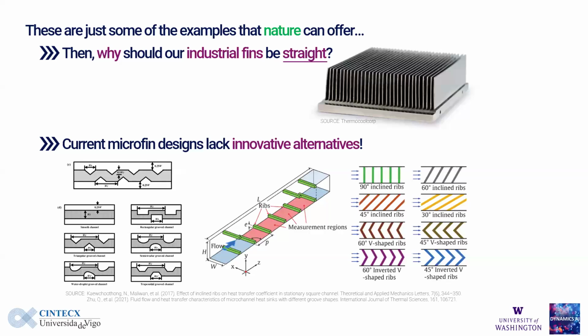Currently, and at the beginning of this research as well, microfin designs and fin designs in general lack a lot of innovative alternatives. As I've mentioned, most of the alternatives that were published were regarding regular shapes, mainly because it's difficult to manufacture anything other than a rectangular fin. Most of you might know that nowadays there's a lot of progress with additive manufacturing, and that's something that we wanted to use for this project. So the idea is, could we propose a fin that is better than what we have nowadays, and use additive manufacturing tools in order to manufacture it?